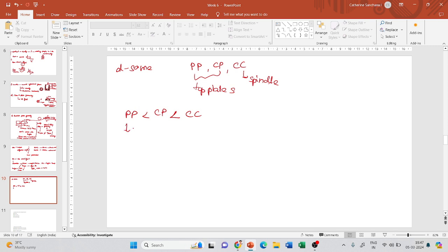And as Gala sir would have said, this parallel plate is used mostly for viscoelastic solid like materials. This is used for low viscosity or viscoelastic fluid like materials, and this is used for Newtonian or very low viscosity samples.